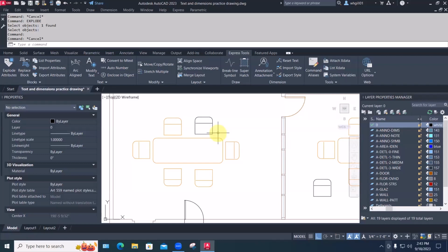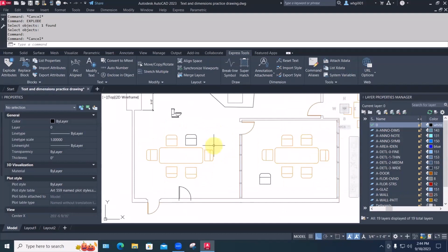I'm going to skip over this thing with blocks with editable text attributes because we're going to deal with them in our exercise in a minute or two. But I want you to start building a library of blocks that are useful to you. We will do this a lot more in Revit, where what comes with Revit isn't going to be exactly the piece of furniture you wanted. So you can modify one of theirs and save it with a new name, or you can create your own from scratch. And with AutoCAD, we can take any block that we've created and save it out as a separate AutoCAD file that can then be loaded into any other drawing. So you start building your own library of the stuff that you've made.